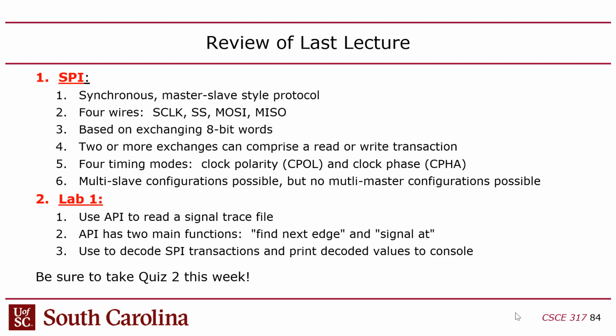And then there are ways to have one master, which is like the CPU, and then multiple slaves. There's 2 different ways to arrange that. You could either do it as a daisy chain, or you can have multiple slave selects that go out to each slave.